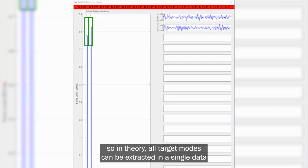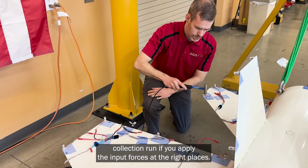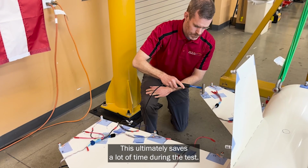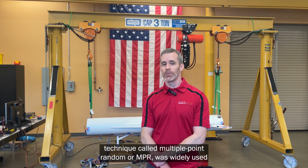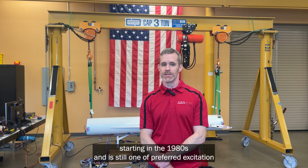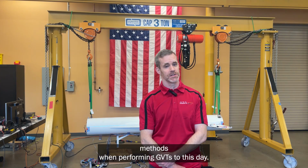Essentially, because the force signals are broadband random noise, they're independent of each other, or uncorrelated as we say, so in theory, all target modes can be extracted in a single data collection run if you apply the input forces at the right places. This ultimately saves a lot of time during the test. This SDRC technique, called multiple point random, or MPR, was widely used starting in the 1980s and is still one of ATA's preferred excitation methods when performing GVTs to this day.